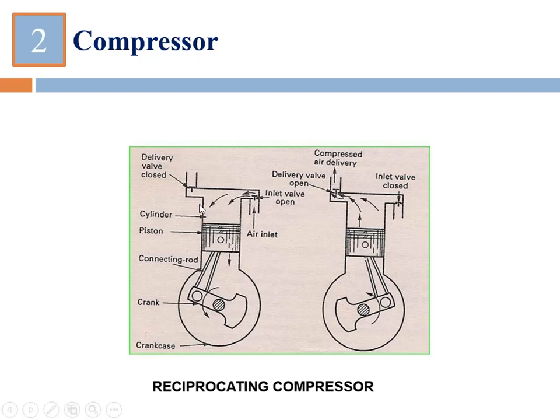So when the piston is moving from top dead center towards the bottom dead center, somewhere here is the bottommost position of the piston where it can reach, and we call it the bottom dead center. In short, the piston is traveling from the top dead center to the bottom dead center, reciprocating between the TDC and the BDC, and the travel of the piston from TDC to BDC, technically we call a stroke.